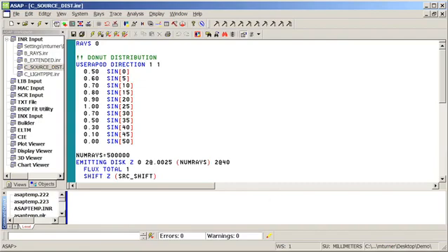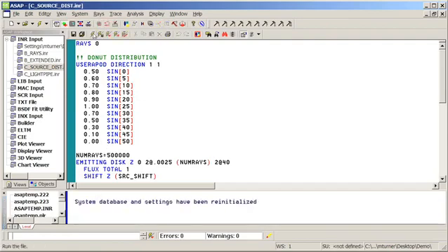What we're going to look at in this case is a problem where we're going to optimize for fiber coupling efficiency. But in this particular case, rather than having something like a simple point source, we actually have a directionally apodized energy distribution. And I want to show you what the energy distribution looks like so you can see the complexity of the problem we're solving.